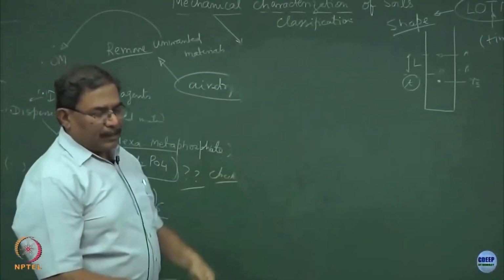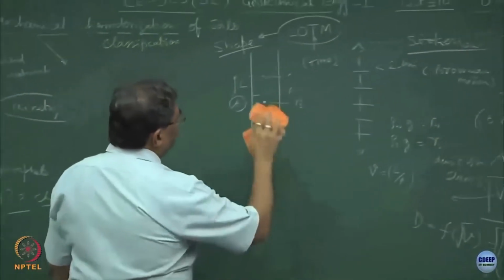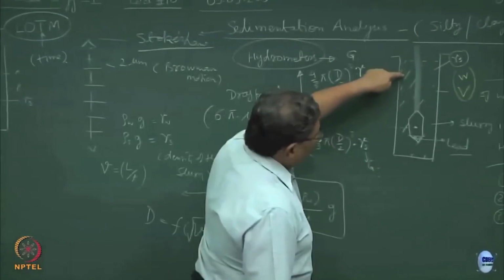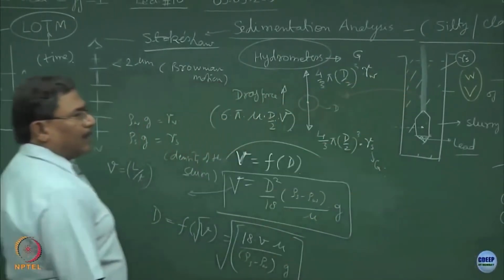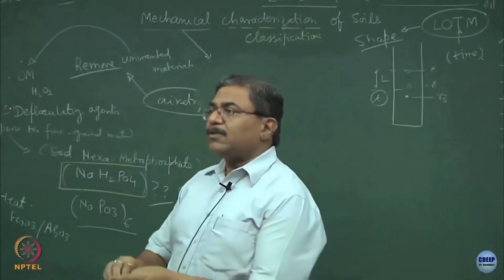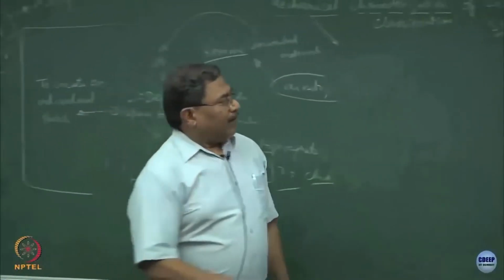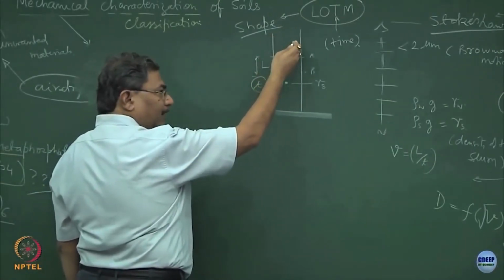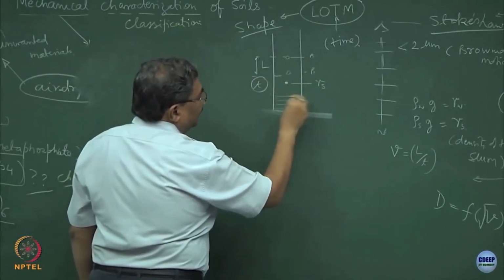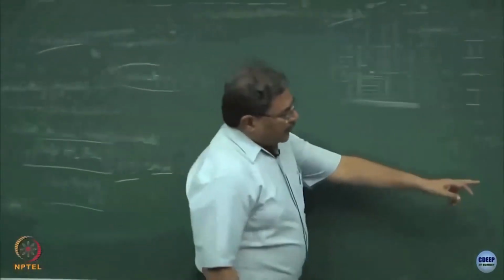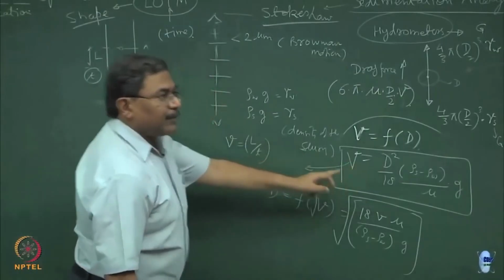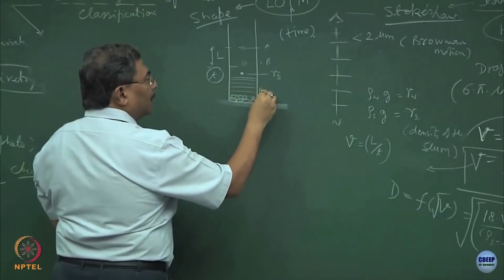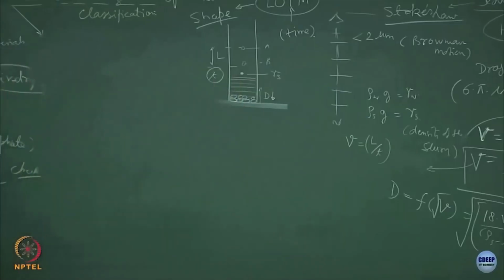This is one concept. In conventional geomechanics, when we are dealing with the hydrometer, we are not going to use this concept much, unless somebody measures in how much time a particular particle during settling is falling from one place to another place. Sometimes it might be visible. You are dealing with a soil, you must have noticed, once you keep it on a flat bed, the particles start settling down and the topmost water becomes clear, and you will have sediments getting deposited over here. Now, this logic tells me the bigger the diameter, the velocity is going to be more. So, all big particles are going to sit here, and as you go up, the particle size would be decreasing. Is this okay? Is this part clear?